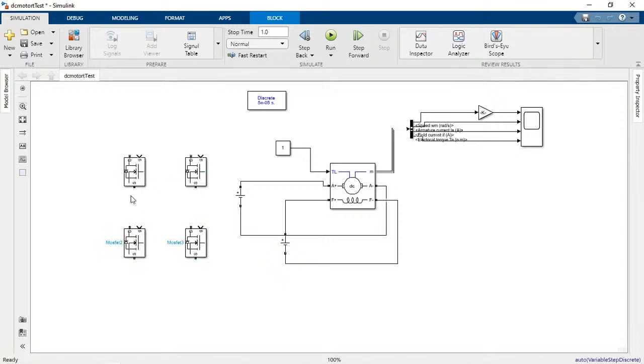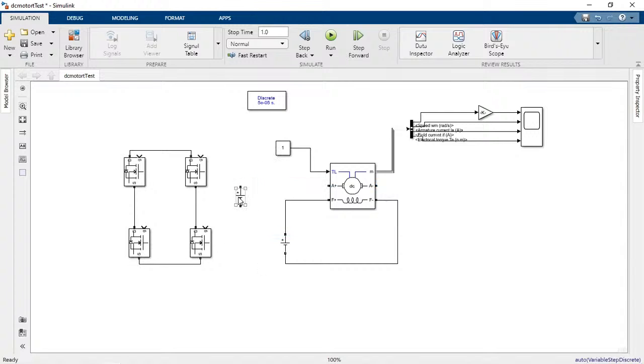By applying the PWM to these MOSFETs, again we can control the speed. But in this simulation, we are going to design the controller for all the modes called forward motoring, reverse motoring, similarly forward braking and reverse braking. So we are going to introduce a braking system also to this motor. Then we can say this is a 4-quadrant control.